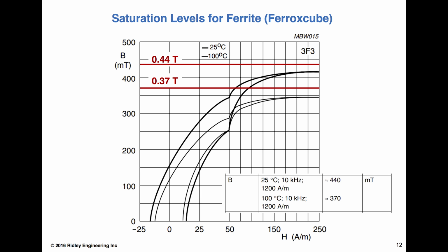And even though planar PC boards seem nice and reliable and a good way to go, a 20-layer PC board with blind buried vias is not a very reliable way to carry a high current. Wrapping a piece of wire is a lot more reliable in terms of getting the current from A to B. So this is what people have discovered, that using planar PC boards, you have to be careful because there are reliability issues and cost issues involved there as well.